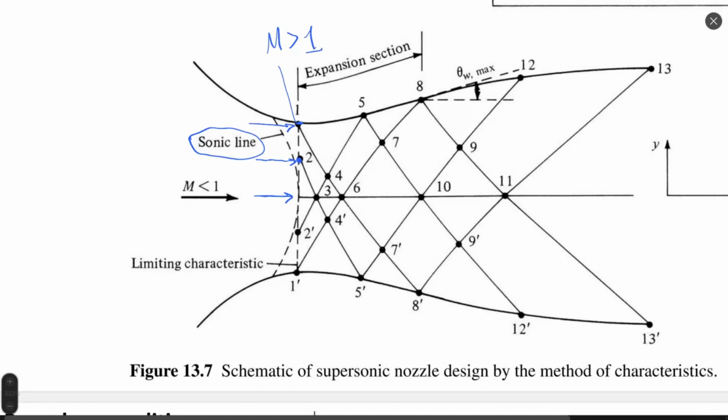It's less likely because we have geometry changing of the nozzle. So probably the first or second Mach number would be bigger, and the other smaller, but it will not generally impact the calculation of the nozzle. We can assume small supersonic velocities, even as small as 1.1 or 1.2 Mach already allows us to use method of characteristics.